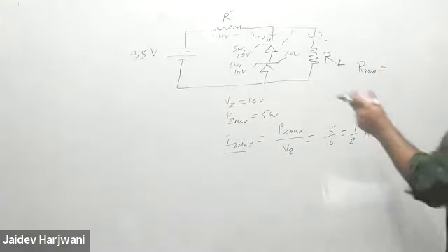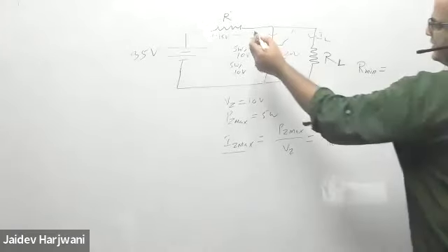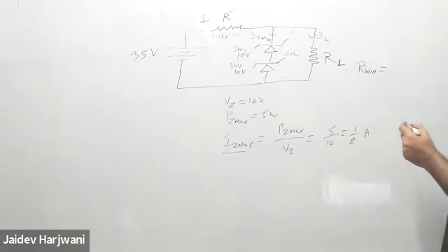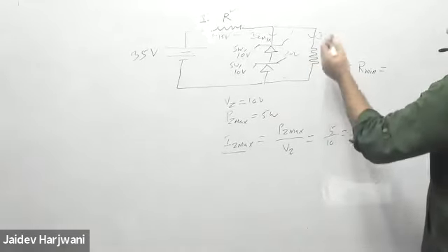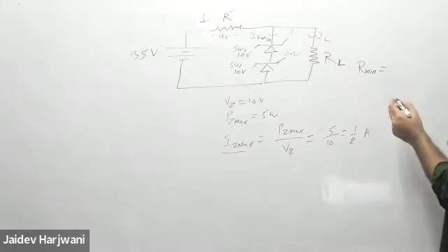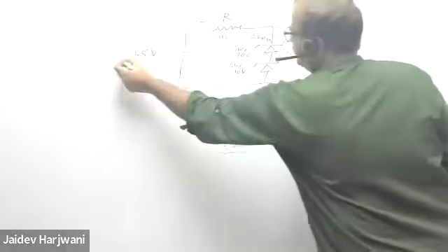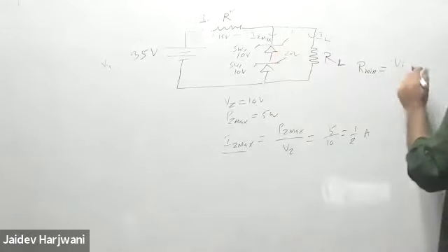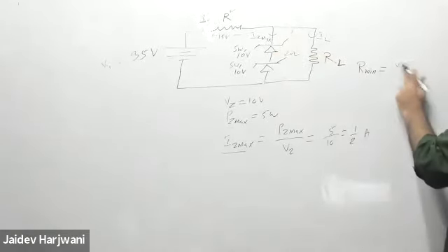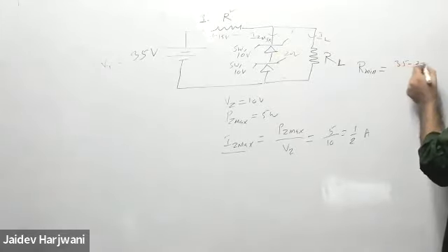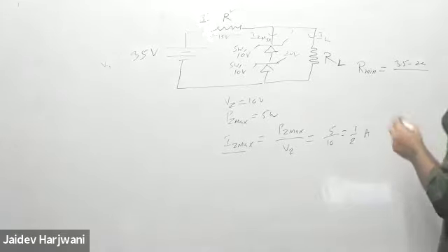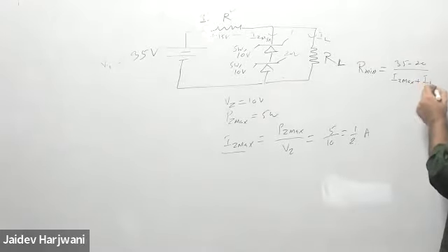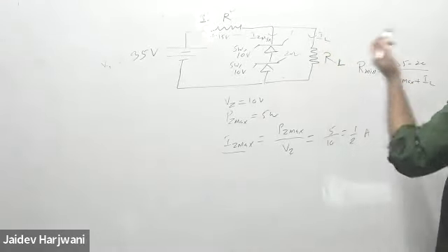That will be voltage drop here, IR. Say current is I, total current is coming IR. And now this is also variable. So now R minimum will be, tell me what will be this. This is the V input minus this is total voltage VZ, 2 VZ basically. So I can directly write 35 minus 20, and I is your IZ max plus IL. Because IL is fixed now, but RL not given.